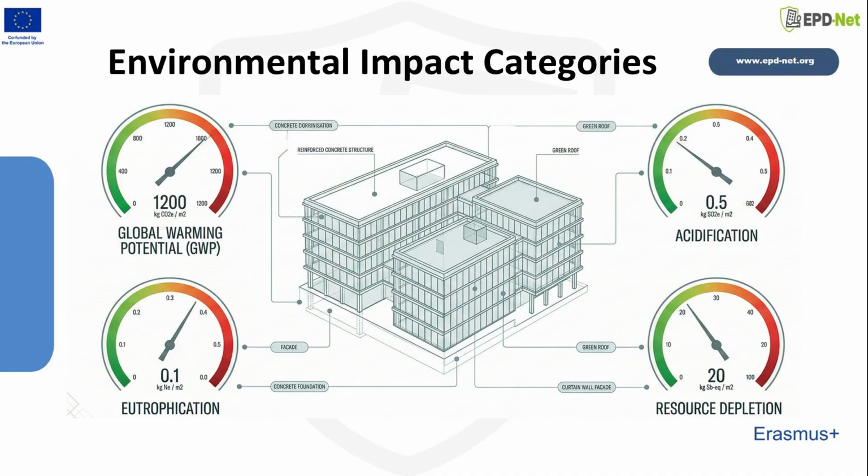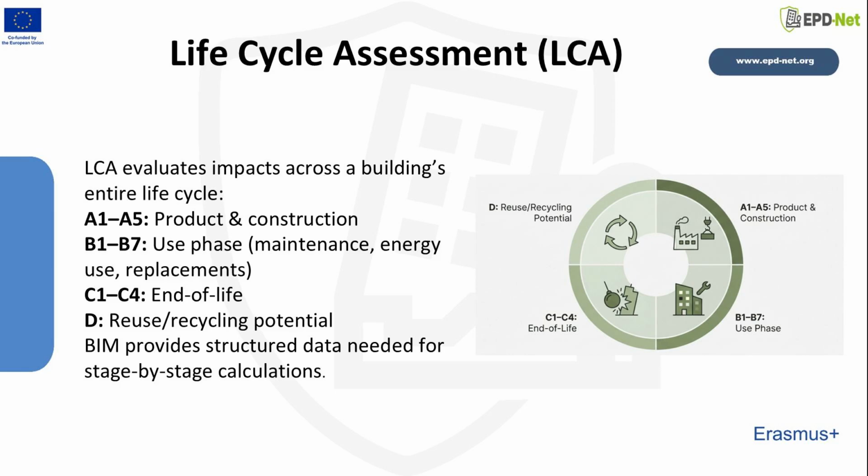By mapping quantities extracted from BIM to LCA databases, designers can evaluate how alternative materials, construction methods, or energy strategies influence environmental outcomes. Life cycle assessment is the scientific backbone of environmental evaluation. Standards such as ISO 14040 and EN 15978 define methodological stages and system boundaries.